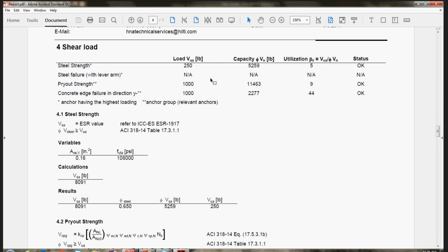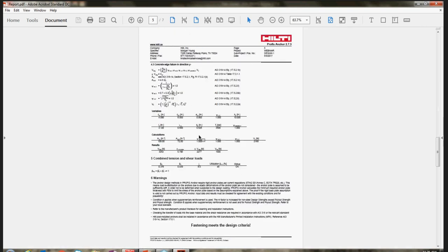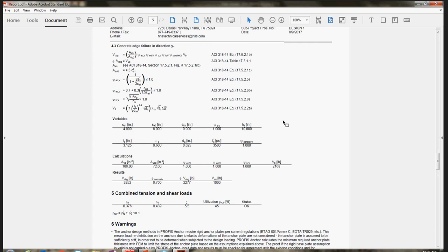So I'm going to open up these tension and shear capacities just a little bit more, because earlier in the presentation Brian talked about load and resistance factor design, where we're looking at these 6 different failure modes and evaluating each one, finding which one controls, and then taking a look at our tension and shear combination by which failure mode is controlling. Okay, so here we have a nice layout, and it's live. Every time we make a change in loads, it's live, and it's showing us that factored load provided by the design capacity that our design is going to see.